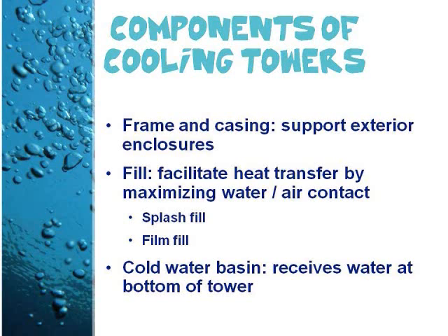Most towers employ fill, which is made of plastic or wood, to facilitate heat transfer by maximizing the water and air contact. There are two types of fill. Splash fill, in which water flows over successive layers of horizontal splash bars, continuously breaking into smaller droplets while also wetting the fill surface. Plastic splash fill promotes better heat transfer than wood splash fill.